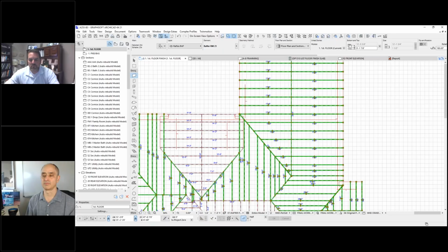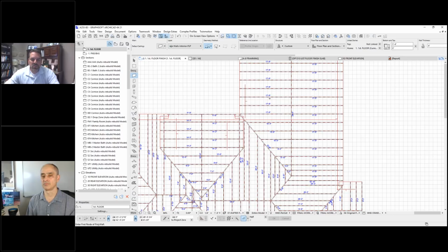Typically it gives you the basic elements, but we also attach a flag to it, which is a label, but the label has no 2D elements to it, so it doesn't show anything. That's how I attach to be able to extrapolate information from the object itself. If you associate a label to it, you're able to pull the information from the object and it becomes parametric. Anytime you change it, it'll update.